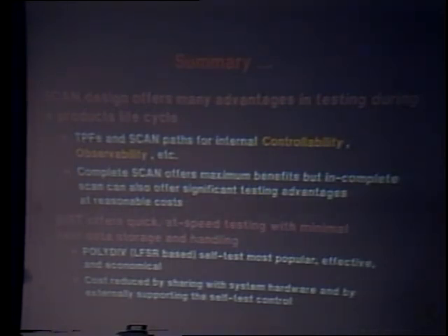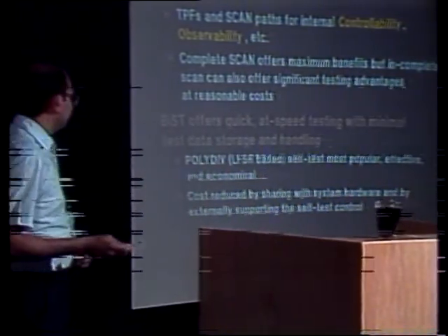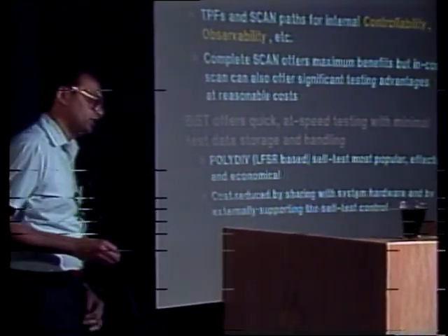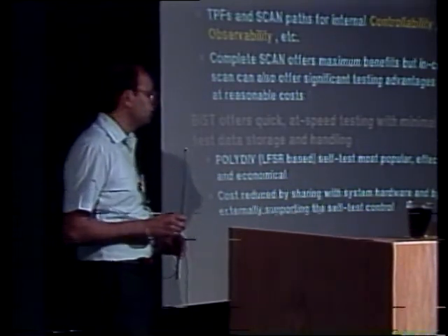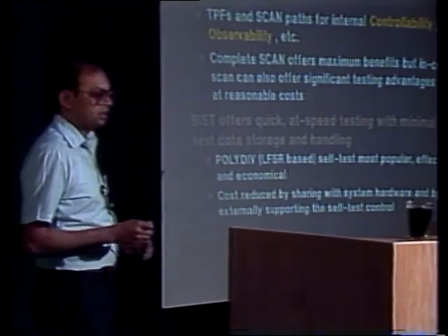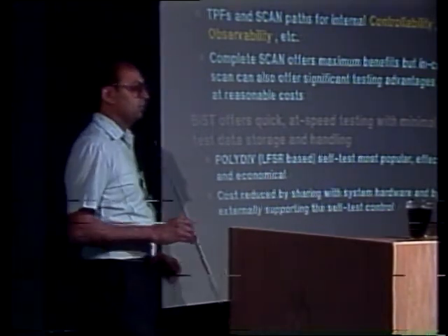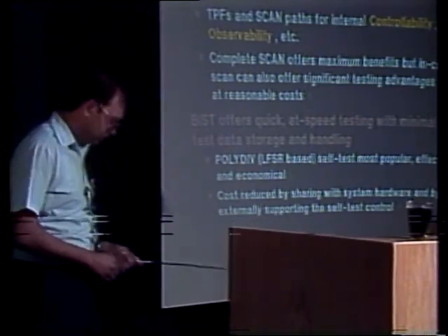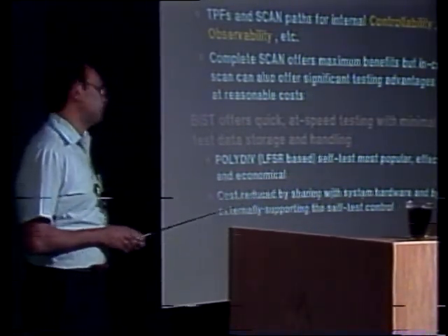In contrast to that, built-in self-test can offer at-speed testing with minimal test data handling and storage requirements. And linear feedback shift register techniques seem to be the most popular, most practical ones. You go to test conferences year after year, and you still hear people working with these techniques, and not many new techniques have emerged. Not a single new technique has emerged really.